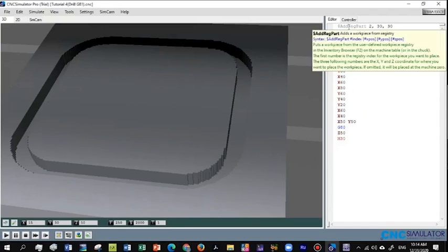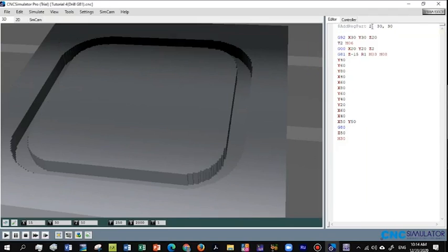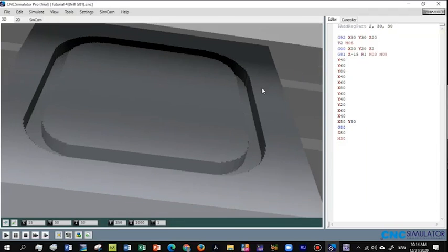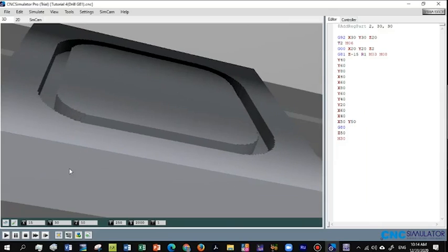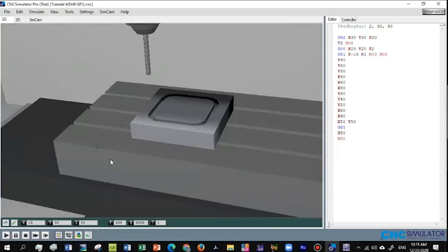So in this case, we can create the holes in the workpiece. As usual, you need first to define your workpiece and the place of your workpiece here. Then you need to define the point of origin for the workpiece itself with respect to the origin of the machine. Here we use G81, which is the canned drill cycle.